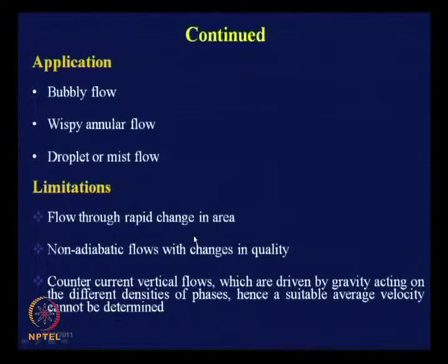So, therefore, whenever we encounter any situation where there is a flow through a short nozzle or an orifice, where there is rapid acceleration, flow through rapid change in area, under such circumstances, since the equilibrium condition is not valid, we do not have the homogeneous flow theory. Okay. So, certain specific cases I would like to read out: flashing of steam water mixture through short nozzles and orifices. We cannot use the homogeneous flow theory.